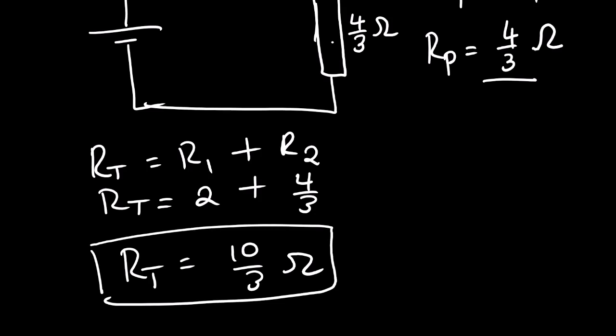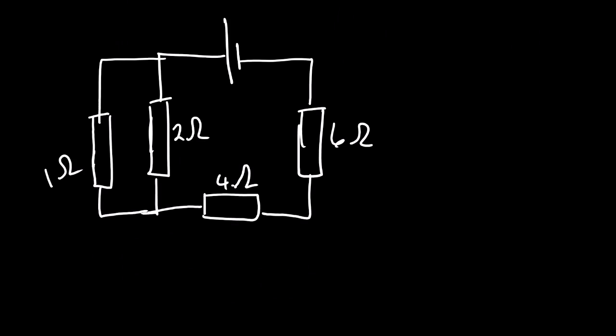Let us look at another example. This is our next question. We still going to calculate the resistance. Now we see we have positive and negative terminal. It's a bit difficult for one to actually understand the parallel and the series in this case. Now we need to look at the direction and the behavior of the current again. It moves, it reaches this point, it must split, then we can identify the parallel connection.